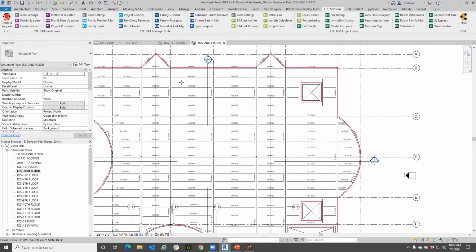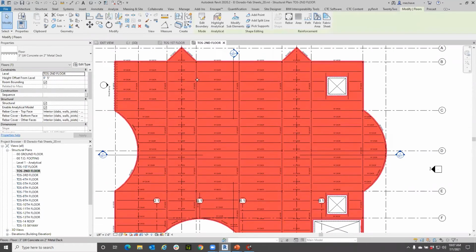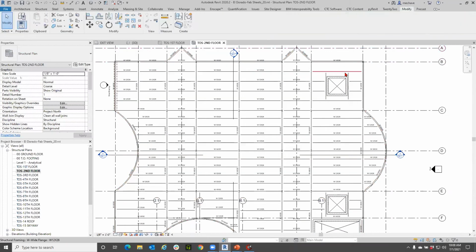Now I'm going to select the floor. Natively in Revit, you have the ability to divide things into parts. This can be for paneling, for precast panels, or even tilt panels, where you're casting on site and then lifting them. But I'm going to be going into here and creating what we call parts. So you go into the create panel. I've selected my elements. This can still be done from the modify tab under the create panel.